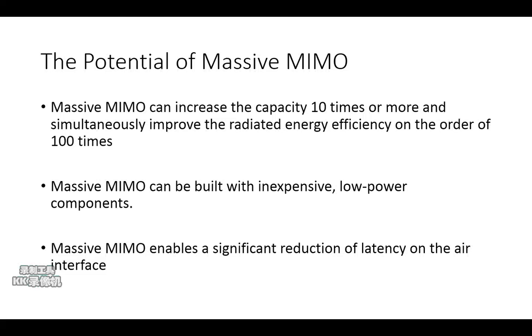The contrast with classical array design, which uses few antennas fed from high-power amplifiers, is significant. Several expensive and bulky items such as large coax cable can be eliminated altogether. The typical coaxial cables used to tower-mounted base stations today are more than 4 cm in diameter.